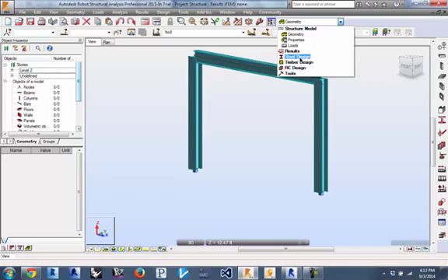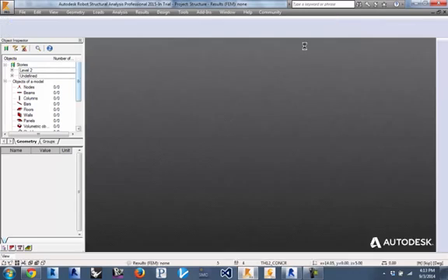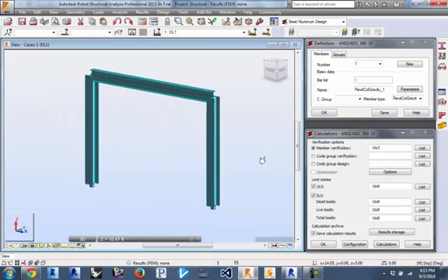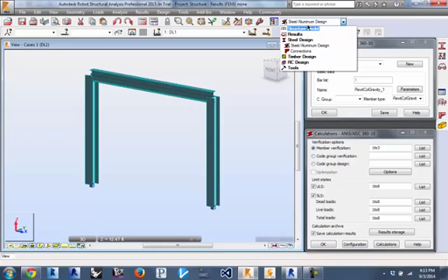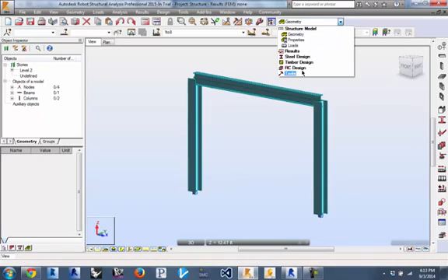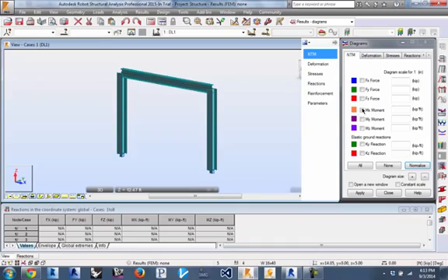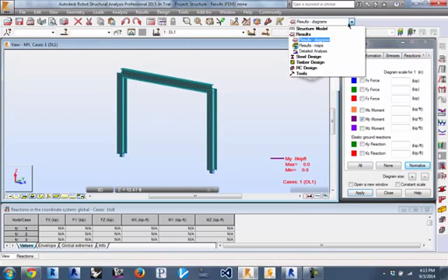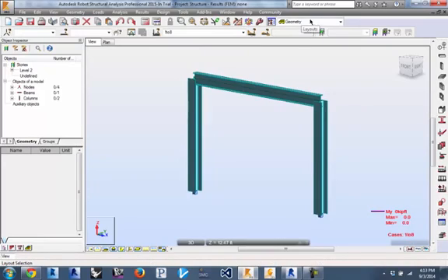If you select steel design and then steel aluminum design, it'll flip over to the design screens. To get back to that, you go back up to this menu and you can go back to the structural model and geometry. So you'll have the different concrete and the different steel, but in navigating, this is generally how we'll get around. We'll have results. When we start running results, I don't think we have anything at this point. So nothing's run. So back in the geometry,